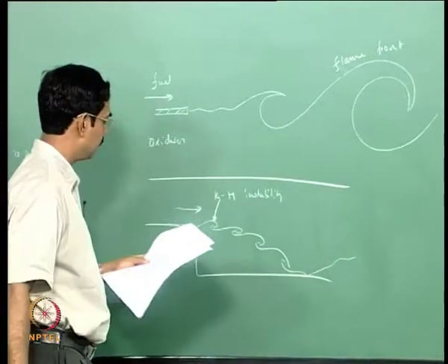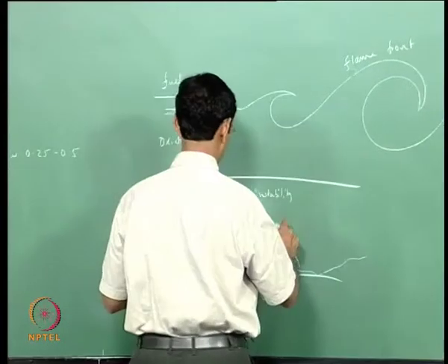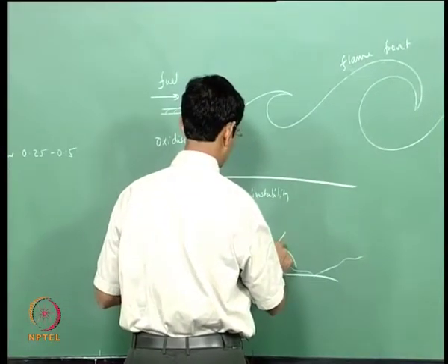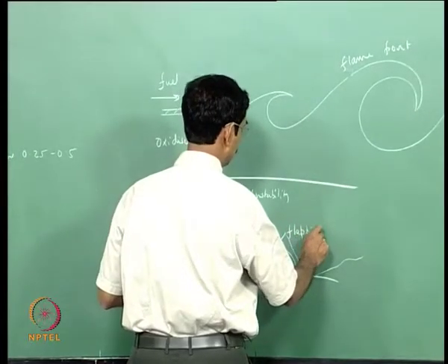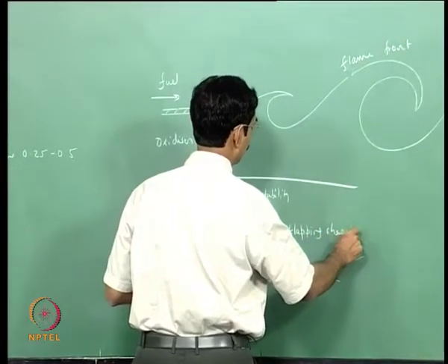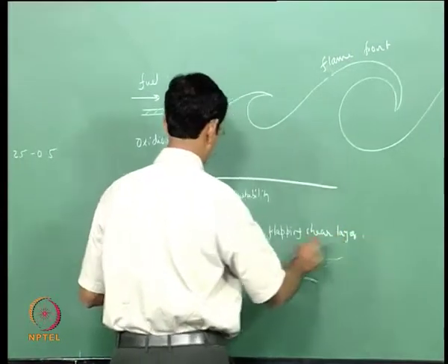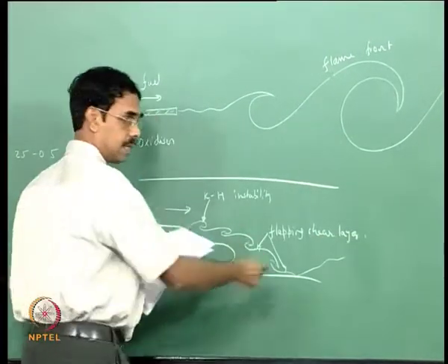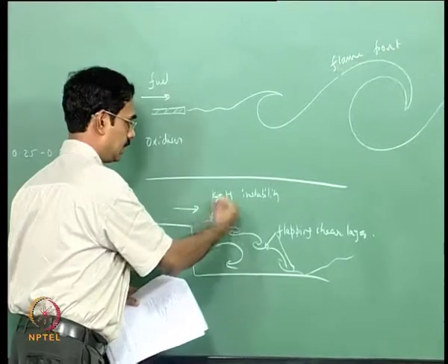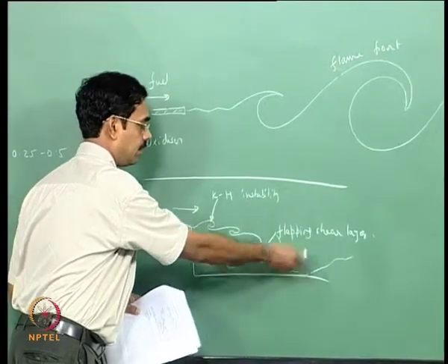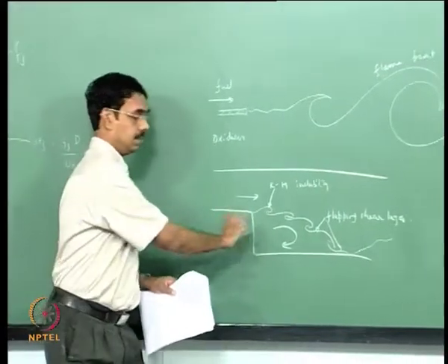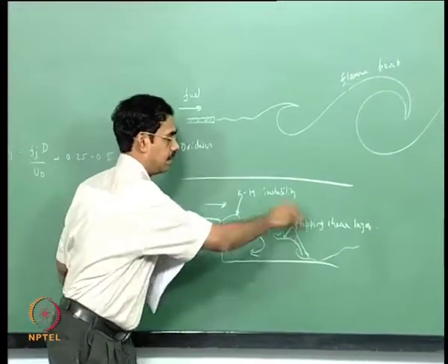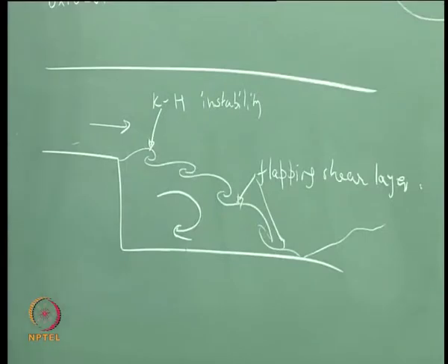In fluid mechanics people often call it KH instability, and then you can also have this flapping shear layer. That is another kind of instability. It can start off with the KH instability, but then you have the step instability. This is for a low step size. If it is very big, then this won't happen, you just roll up without interacting with the vortices.